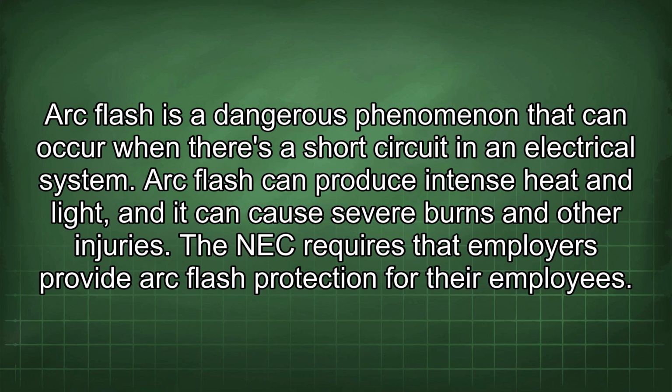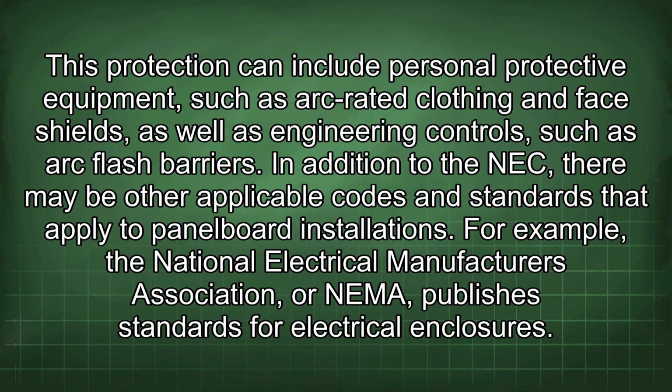Arc flash can produce intense heat and light, and it can cause severe burns and other injuries. The NEC requires that employers provide arc flash protection for their employees. This protection can include personal protective equipment such as arc-rated clothing and face shields, as well as engineering controls such as arc flash barriers. In addition to the NEC, there may be other applicable codes and standards that apply to